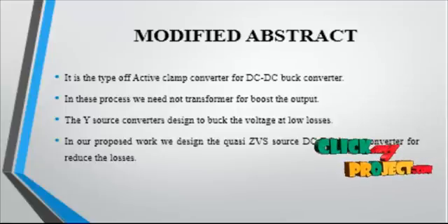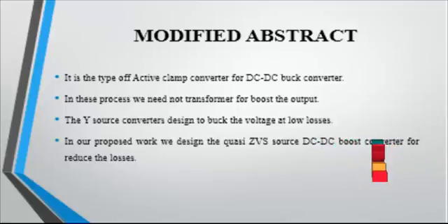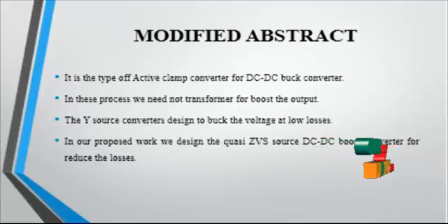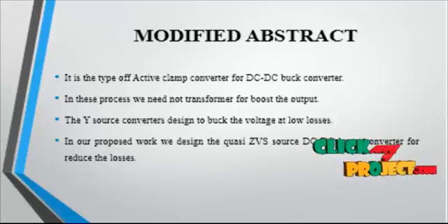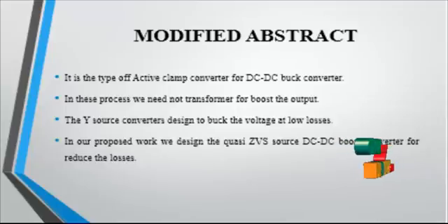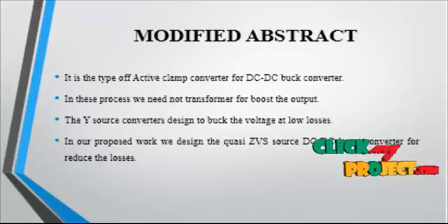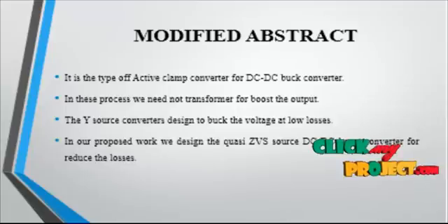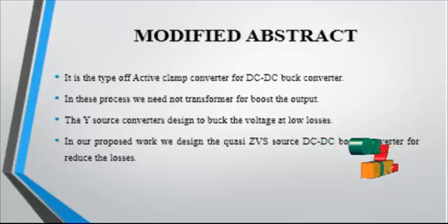It appears that the stability region in current controlled active clamp converters gets extended for duty ratios a little greater than 0.5, unlike in conventional hard switching converters. The conventional graphical approach fails due to the coupling between the filter inductor current and the resonant inductor currents.